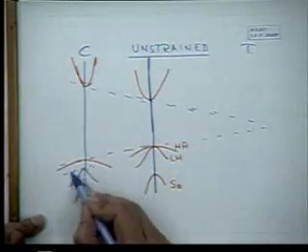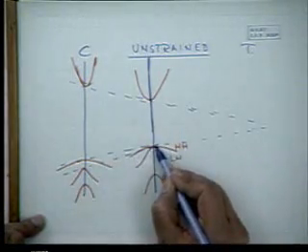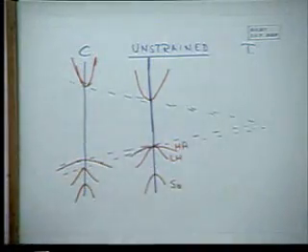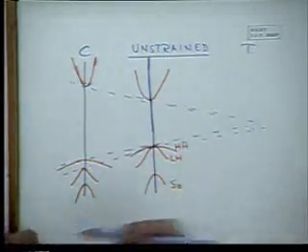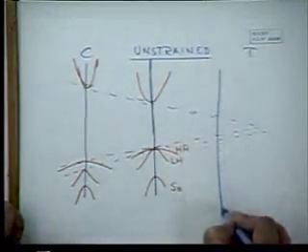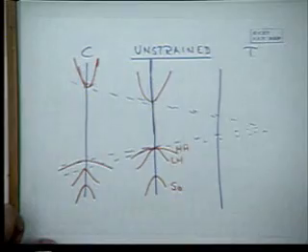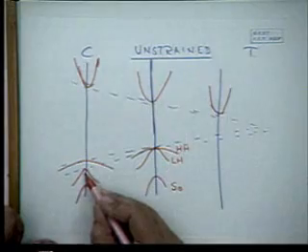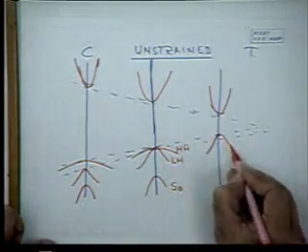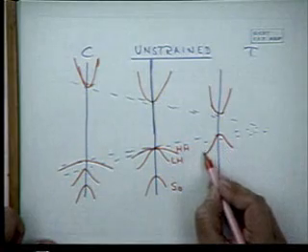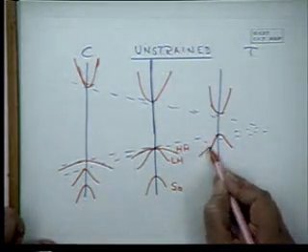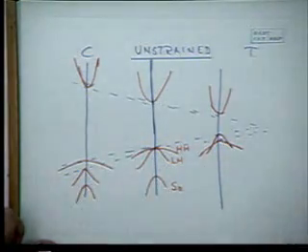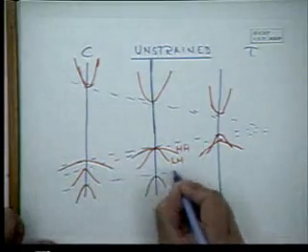And with tensile strain, this is the unstrained region, and it will go say something like that. This is a little exaggerated. However, if I draw the strained region somewhere here, tensile, what happens? The band gap decreases, and here it is the light hole band which is on top. The heavy hole band is lower, and the split off band also follows a particular variation.